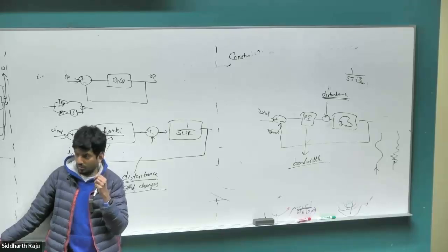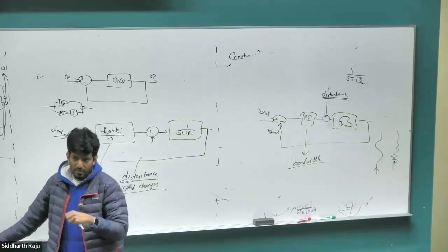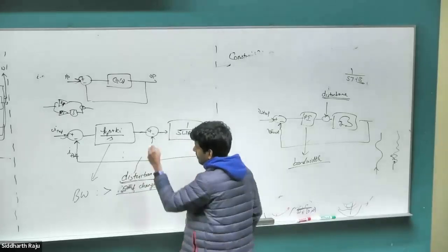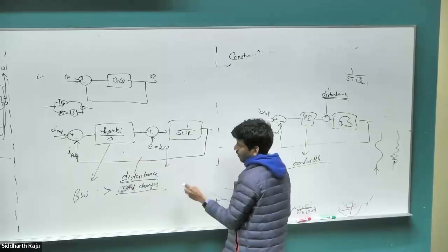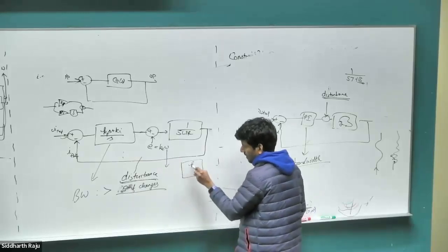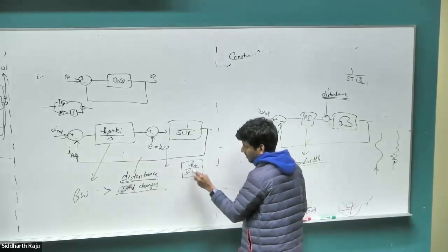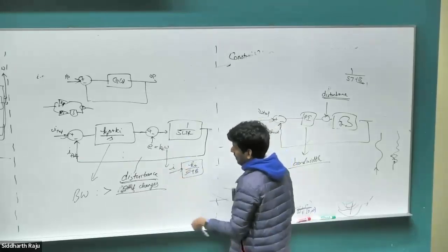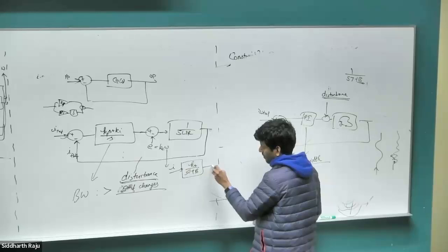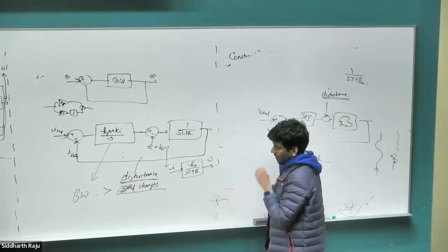It's basically the time constant of a mechanical system and the electrical system. Because what is dictating the EMF? EMF is Ke times omega. And what is dictating our omega? That is Kt divided by Sj plus B, with current coming in. I put the Kt inside because torque is Kt times I. I'm leaving the load torque for now. And then we get omega.